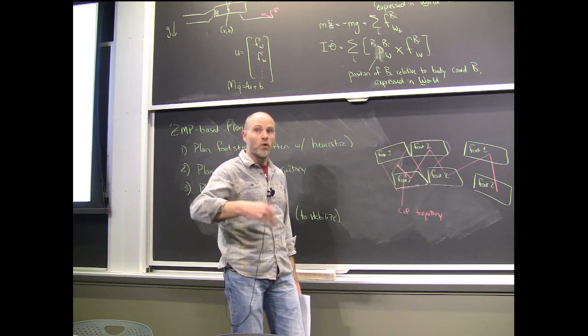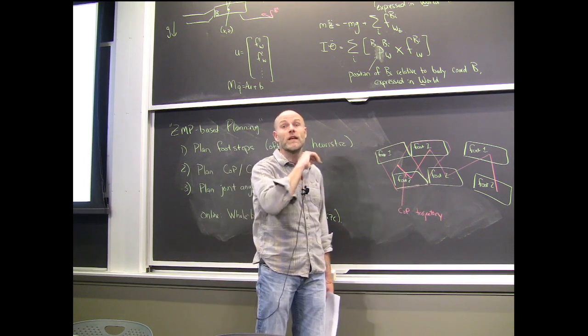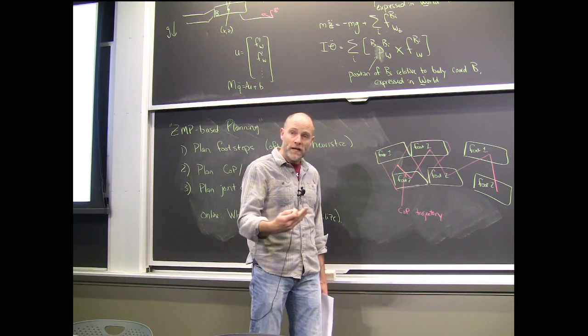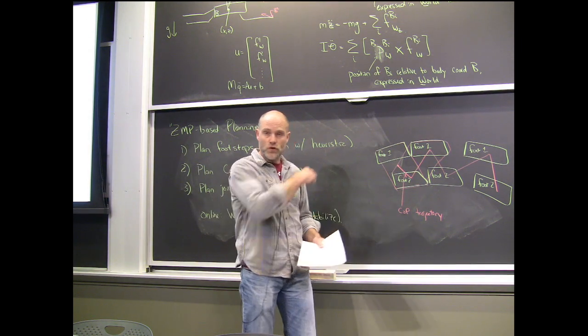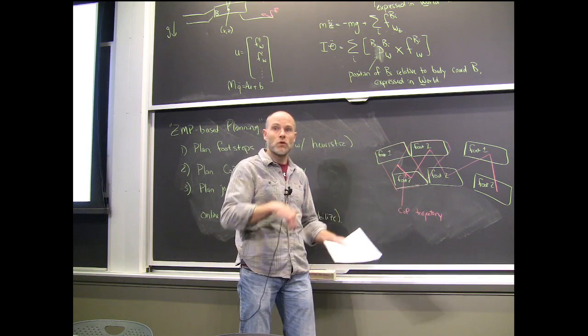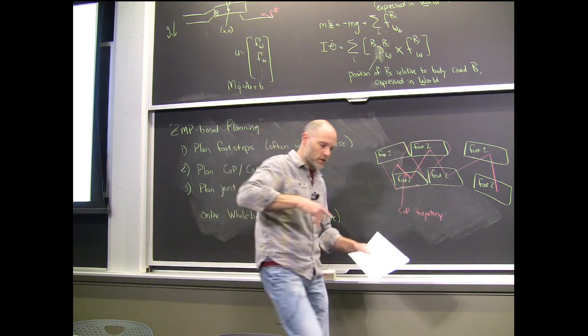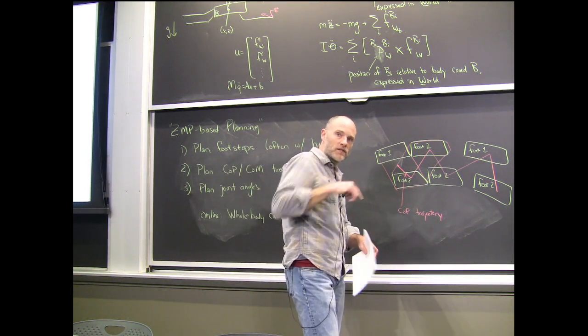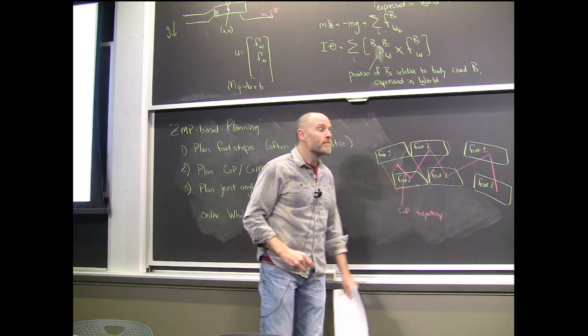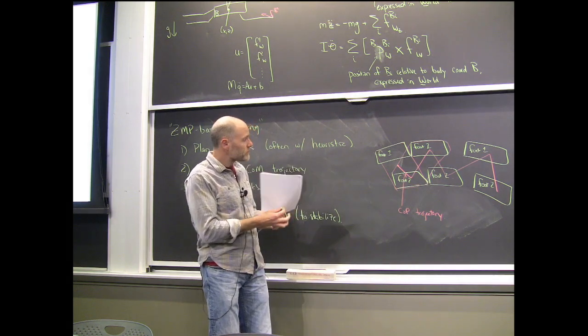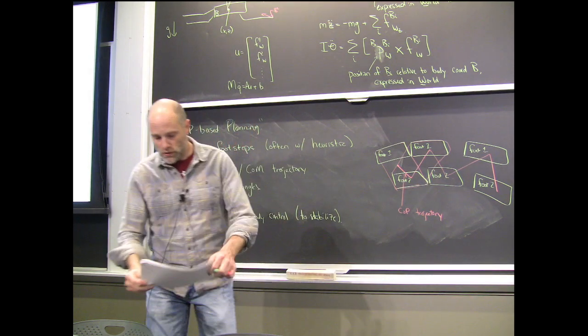And the more you put into the trajectory optimization, the more dynamic you can go. For quadrupeds, for instance, you can have multiple gaits that have non-trivial timings that always have a zero moment point description. You could have diagonal legs on the ground at the same time. Your zero moment point should be on the line as you transition to the next thing. Okay. I need one more color of chalk here.